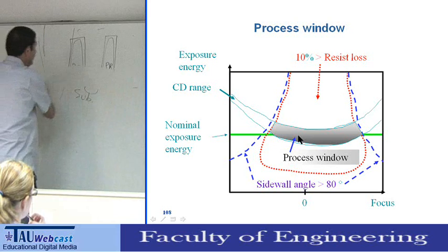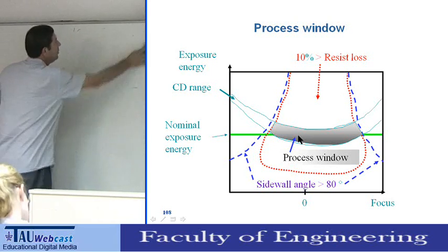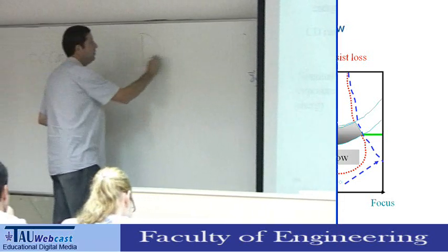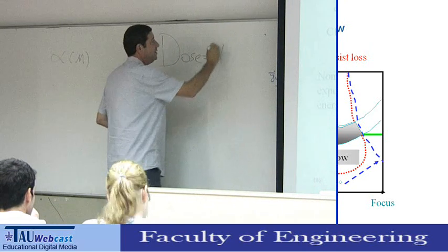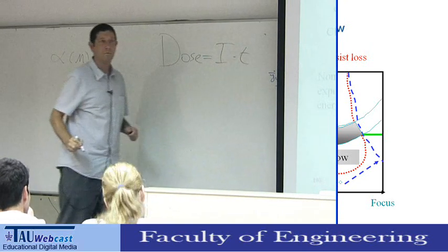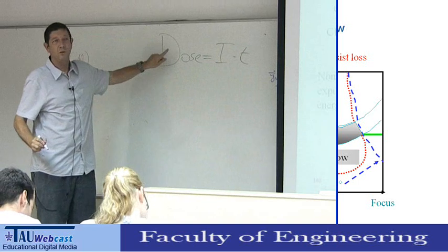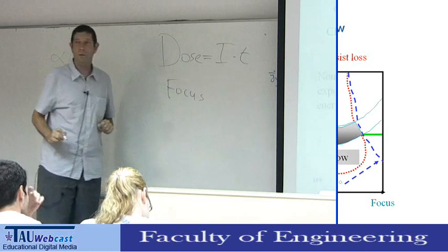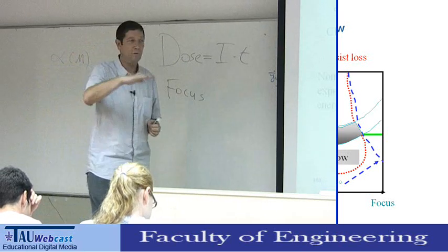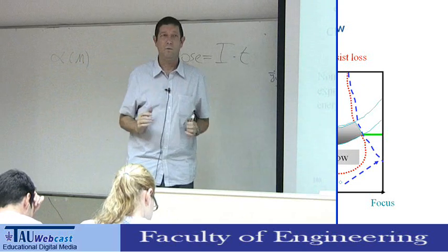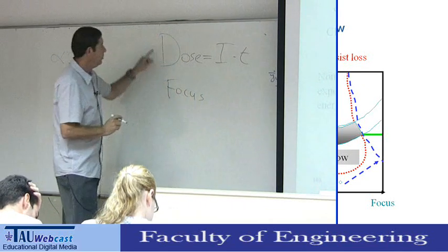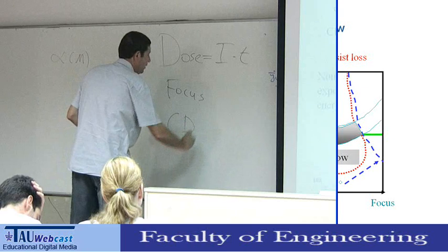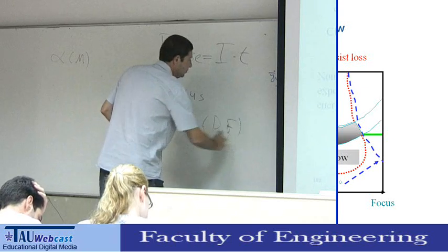If I summarize this lecture, it goes as follows. In a normal lithography process, your line width depends on the dose, which is defined as the intensity times time. And the dose is the most important function. However, the focus also is a problem, because you want to be in the best focus. If you're not in focus, your image becomes of lower quality.